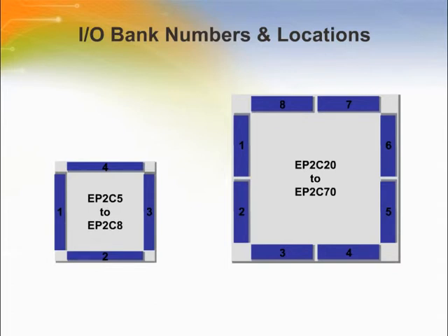To accommodate voltage referenced I/O standards, each Cyclone II I/O bank has a VREF bus. Each bank in EP2C5, EP2C8, EP2C15, EP2C20, EP2C35, and EP2C50 devices supports 2 VREF pins, and each bank of EP2C70 supports 4 VREF pins.